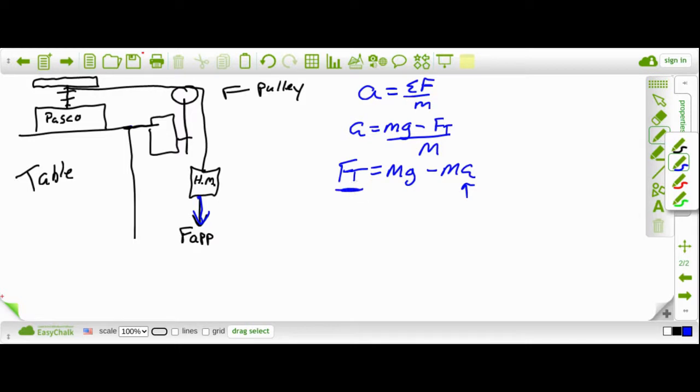This T is causing the torque, and depending on which step of the pulley system we're using, that's going to determine the acceleration of the overall system. Since torque is equal to force times the distance, we know that by changing the radius, we're going to change the overall torque on the system. Again, this force is the tension caused or measured in the system. The step pulley size does affect the overall acceleration.